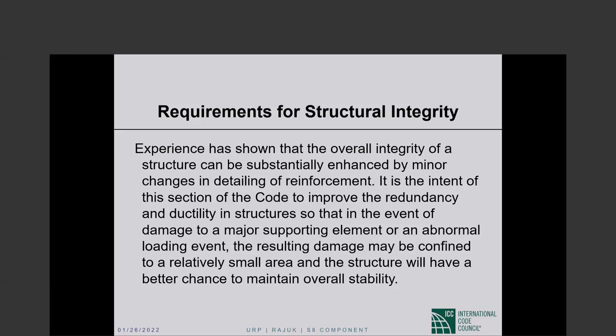You will not have the very tight tie spacings as in the columns of the superstructure. What they are, without checking, I do not know offhand, but they definitely are relaxed. You do not have to provide the same confinement to the pile as you do to the column of the superstructure.